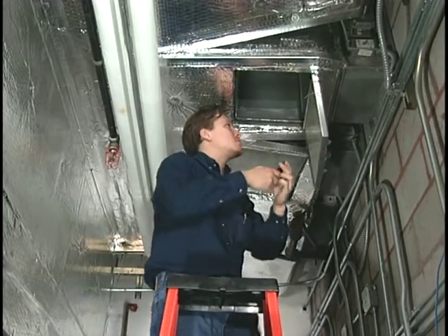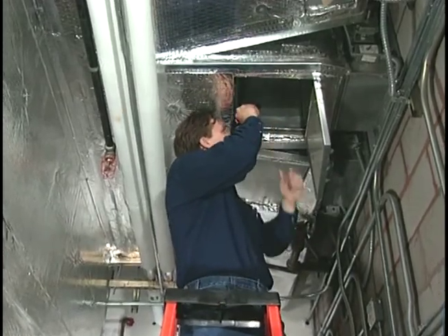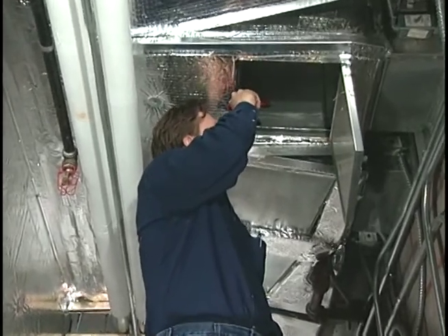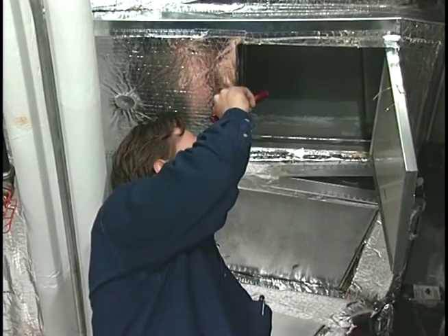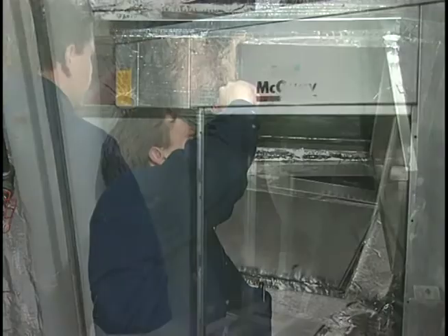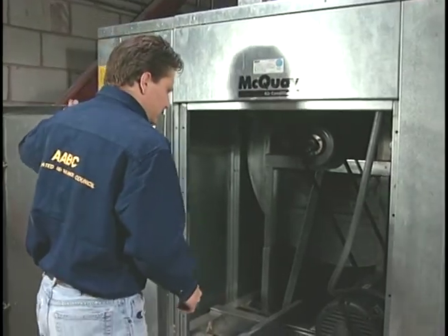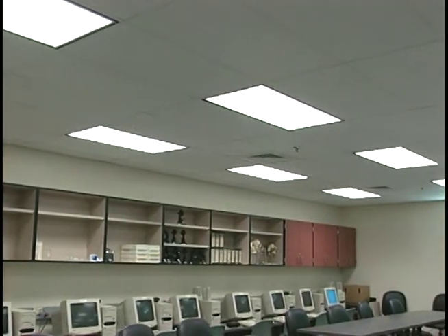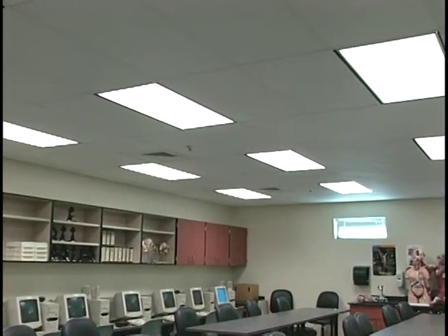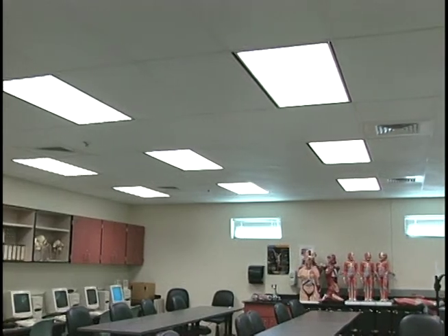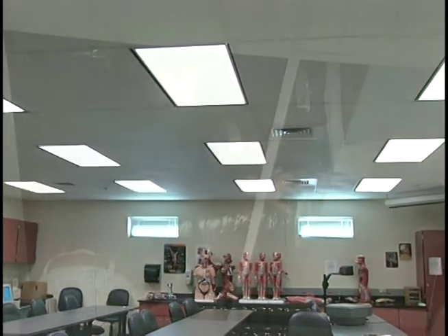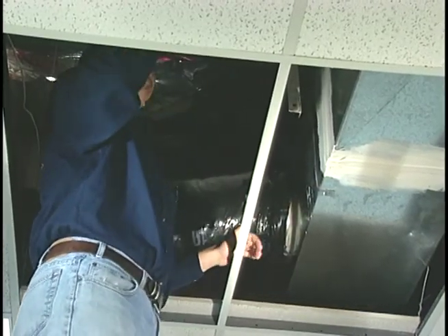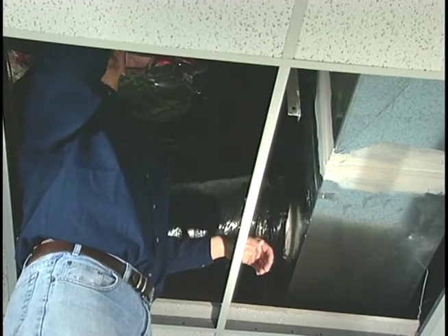Additionally, the technician inspects all dampers, including fire and smoke dampers, to verify that they are installed, accessible, operational, and open. Terminal boxes, reheat coils, electrical reheat components, etc., are checked for installation, accessibility, and operation. Outlets are checked and counted so that none are missing and all are installed as specified. While inspecting the supply and return duct systems, the technician identifies appropriate locations to take pitot tube traverses.